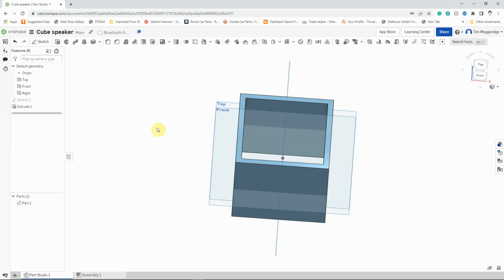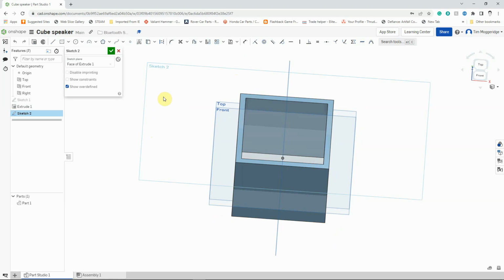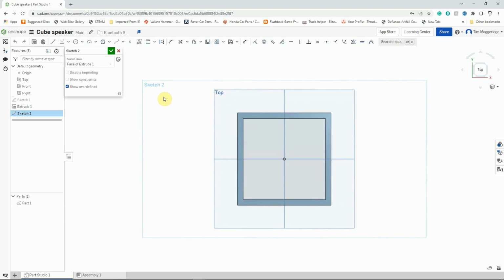Okay, let's add some ends to it then. Let's do a top end first of all. So I'm going to hover the mouse so that I'm between the inside and the outside lines or edges of our square tube. They've both gone orange. So I'm selecting that top face. I'm going to right click, left click on new sketch, and then press the N key to view normal to it. And again, I could create a square.